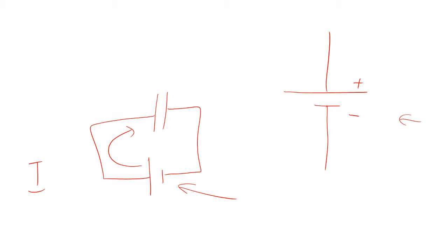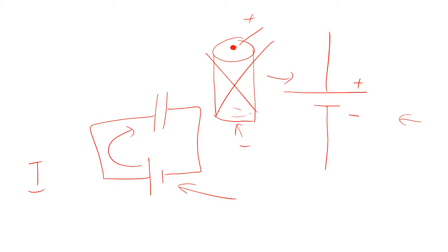And it always confused me as a student because I think of these little dry cell battery type things that you buy, in which the small end is positive and the great big back end is negative. That's exactly backwards of how the symbol is designed. The symbol has the long end positive and the short end negative. So this is our basic power supply. You can think of it as a battery, but it's technically considered a power supply.